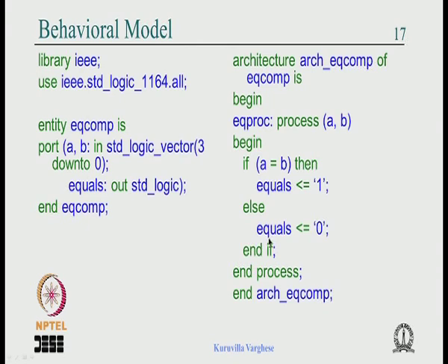That's the idea of a process, and the process uses constructs like if, case, and for loops. So this process body allows you to describe the behavior of the circuit in a behavioral fashion using higher level constructs like if, case, for loops and all that. That is why it is called the behavioral model.